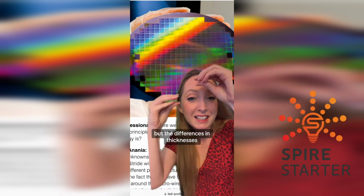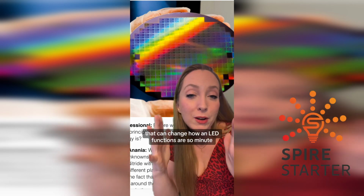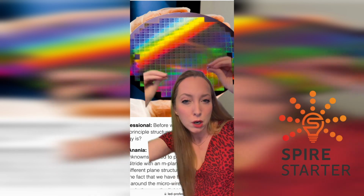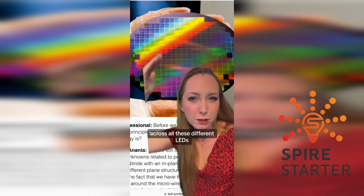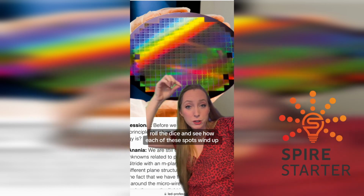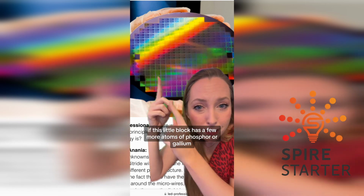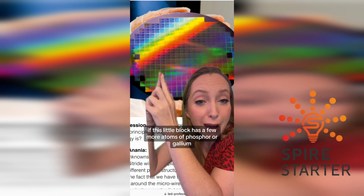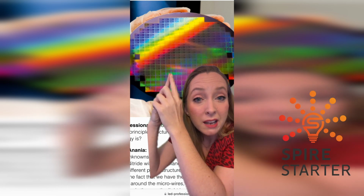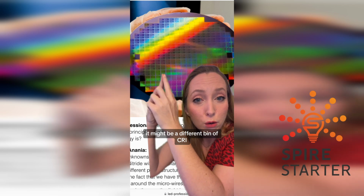But the differences in thicknesses that can change how an LED functions are so minute that they can't just force them all to be one color temperature, one efficiency across all these different LEDs. So they just kind of roll the dice and see how each of these spots wind up. If this little block has a few more atoms of phosphor or gallium or whatever is in the chemistry to change the colors for that formulation, compared to this one right next door, it might be a different bin of CRI.